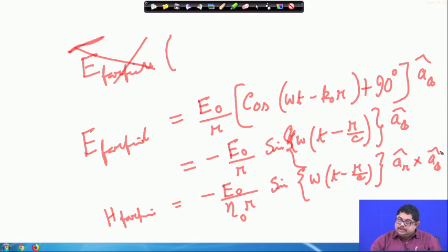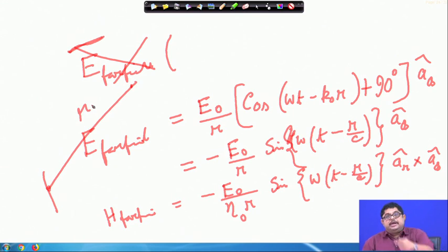So, this also shows that in time domain the fields are delayed by r by c. That is obvious. If I have a current here, then it requires some time to go to this point, the fields do not reach immediately. So, this is the delay, that delay corresponds to the distance r, and it propagates with the velocity of light. So, the wave has a finite propagation time to reach a point.